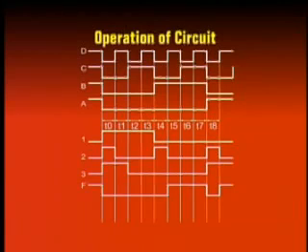At interval T0, the active low input at inputs A, B, C, D is 0, 0, 0, 0, which actually represents 1, 1, 1, 1. The active low output F is 0, which indicates that adjacent ones have been detected.